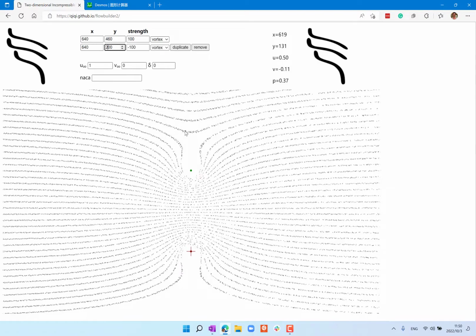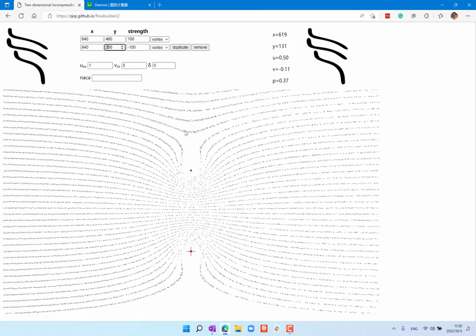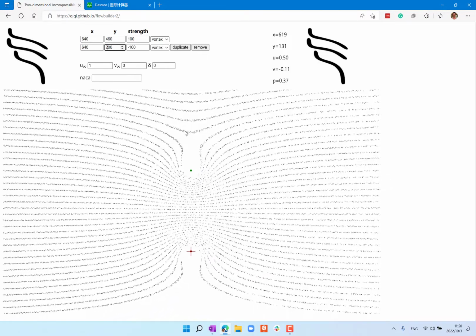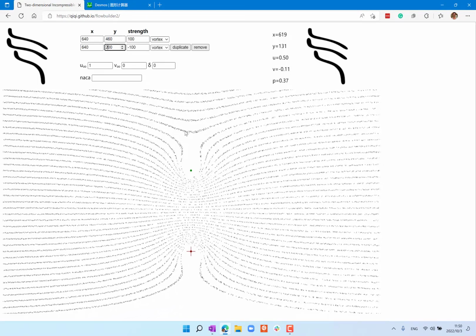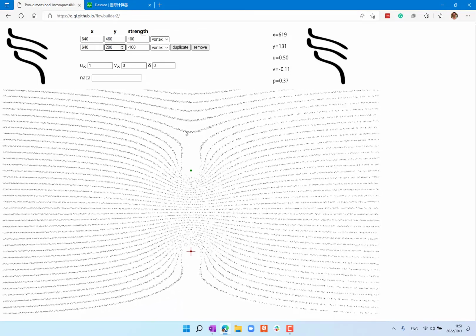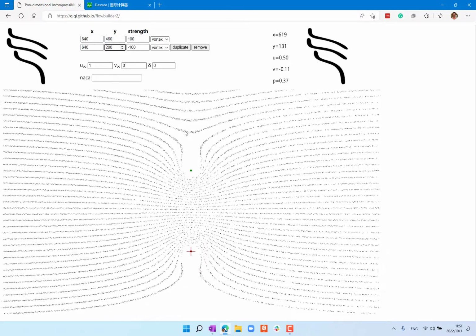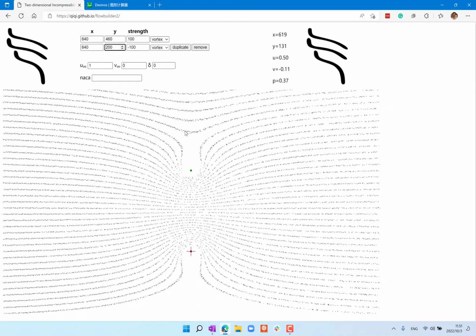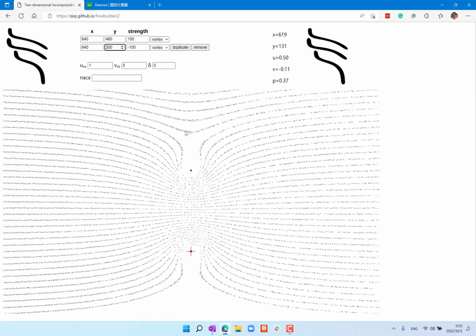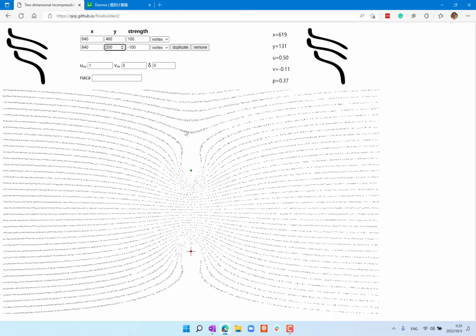Now use Bernoulli, right? If the pressure is highest over here along this line, then the velocity is slowest here along this line. That means it's faster over here. That means the stream tubes are narrower. That means that quarter height particle is going to end up closer to the wall again.